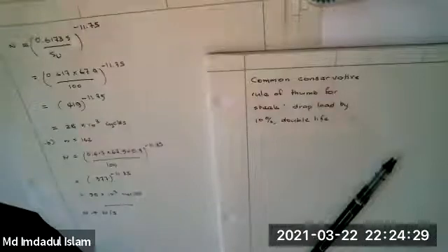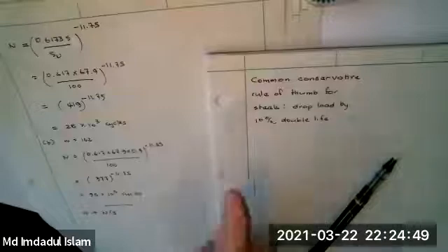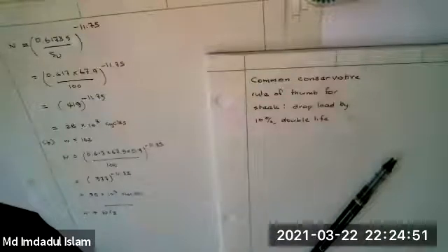Then we just redesigned it, so we dropped the stress by 20%. The life was typically minimum, I recollect, 8 years, maximum about 20. So on average, 14 years, but minimum 8. If you multiply even 8 by 4, and this is a conservative rule, then you get 32 years, which is pretty good. And we could easily drop the stress by 20%.